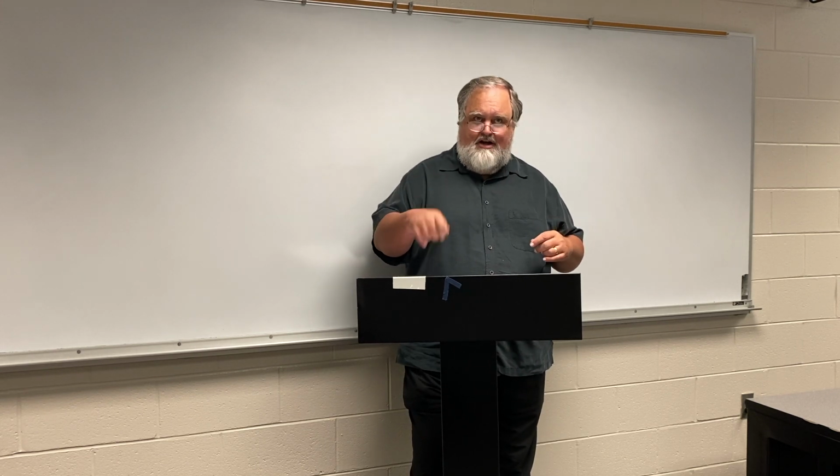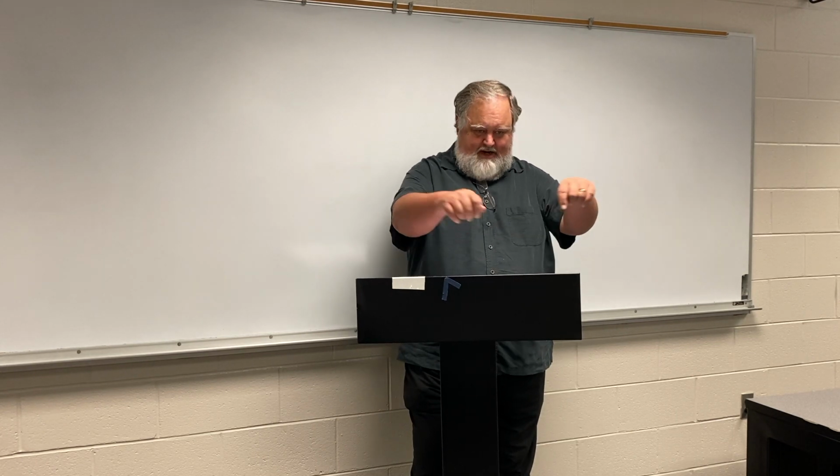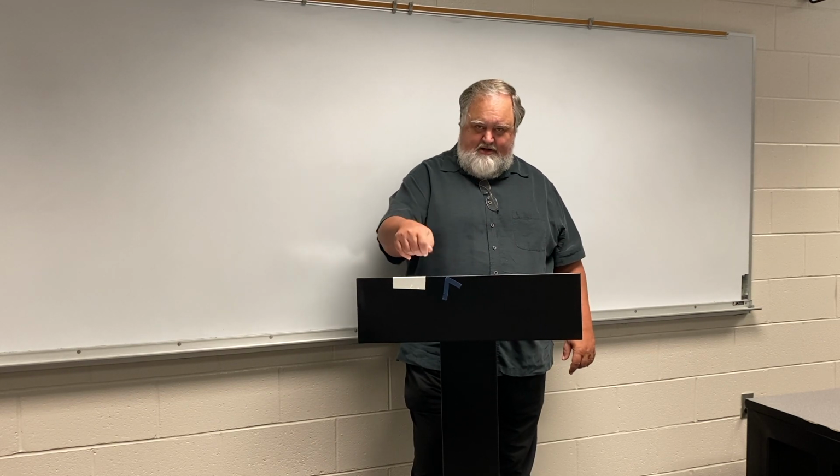So anything other than a standard 4x8 where you just know the sizes already, go ahead and lay out the top full scale in plywood, lay all the pieces of plywood out, draw it out, and then on the top, write TOP. That is the most important part of the whole thing you're about to do here. Lay out the platform, mark it all out. If it's a big cloud that you're standing on, mark out the big cloud you're standing on, and then go around and label all the tops of the platform TOP.